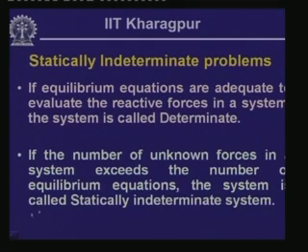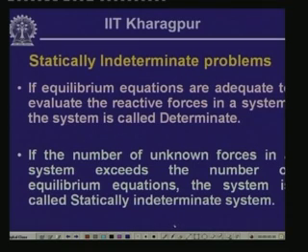Now, let us look into the important aspects which we do come across in many problems related to different fields, which we designate as a statically indeterminate problem. Naturally, we will have to first know what we really mean by a determinate system. We have seen earlier that we have three sets of equilibrium equations in statics: summation of horizontal forces as 0, summation of vertical forces as 0, summation of moments as 0. These are the equations of equilibrium.